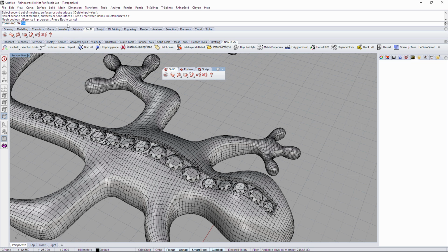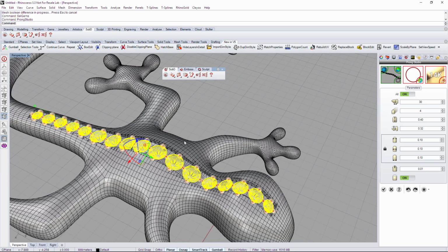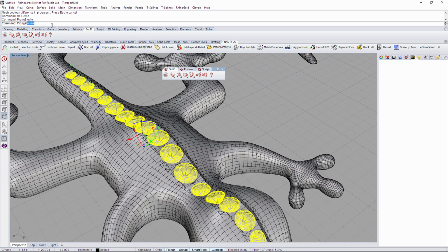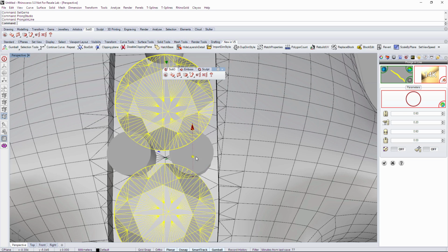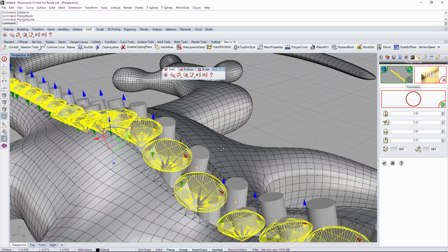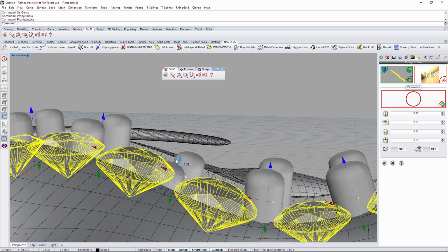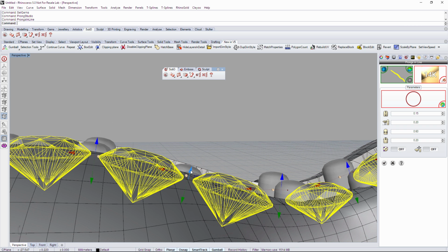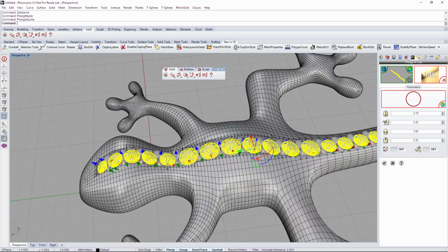Okay, so I'm gonna go to select gems. Okay, and prongs studio. Okay, or maybe we can create prongs in line. Maybe it's gonna be even better. So let's go to prongs in line. I'm holding shift on a prong just to make sure that we are applying the changes to all the prongs in here. Okay, I'm gonna apply a small cap on my prongs. I'm gonna reduce the height a little bit, maybe even more, and holding shift I'm gonna apply changes to all the objects, something like that. Okay, maybe I'm gonna reduce, no, that's okay, 0.6, it's okay for the diameter.